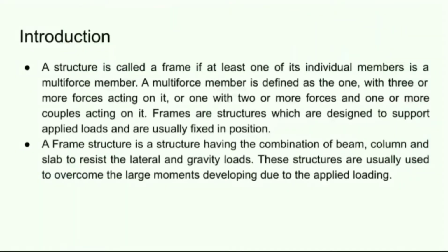A structure is called a frame if at least one of its individual members is a multiforce member. A multiforce member is the one with three or more forces acting on it, or it has two or more forces and one or two moments acting on it. So this is a multiforce member.